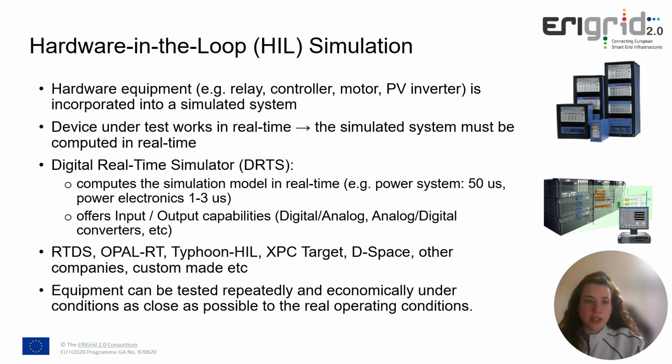A digital real-time simulator has this capability, and it computes the simulation model in real time with a time step of 50 microseconds, and for power electronics it can go down to 1 to 3 microseconds. It also offers capabilities for input and output signals, digital, analog, or communication-based, etc. And some of the most famous simulators are produced by RTDS, OPAL-RT, Typhoon, etc. The equipment can be tested repeatedly and economically under conditions as close as possible to the real operating conditions.